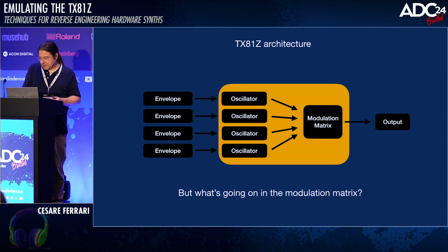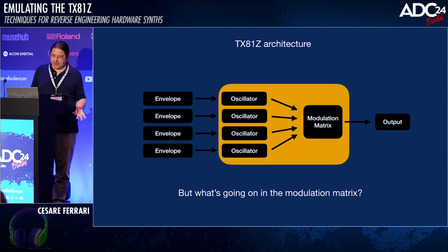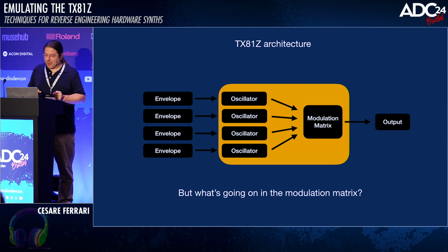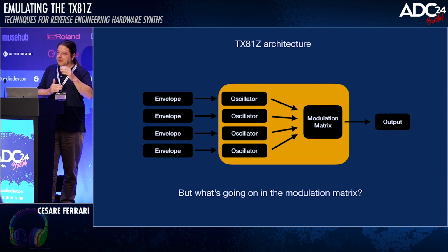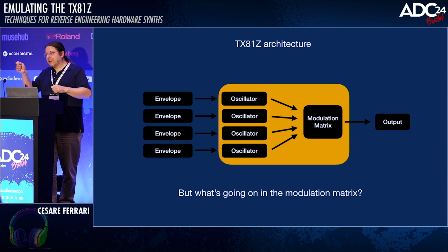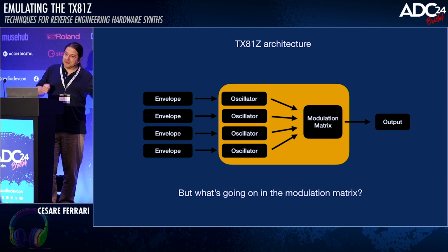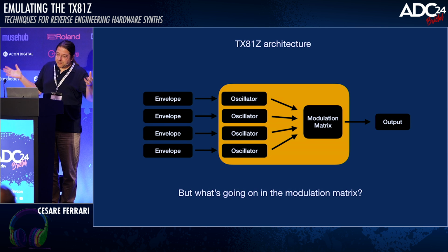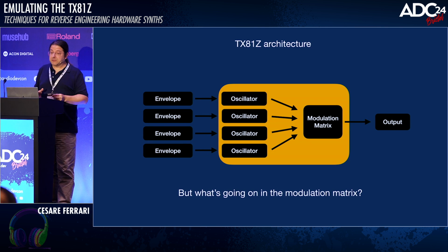So, having looked at the manual, having looked at the parameters that we care about, we've got this basic idea that internally there are envelopes, oscillators, modulation, which is the whole FM thing. Because if you go through the parameters, you find it says oscillator 1 frequency, envelope 1 attack rate. So you can kind of put the building blocks in. So notice that we've taken the whole "what is a TX81Z?" and we've ended up with 3 bits. We need envelopes, oscillators, and a modulation matrix.